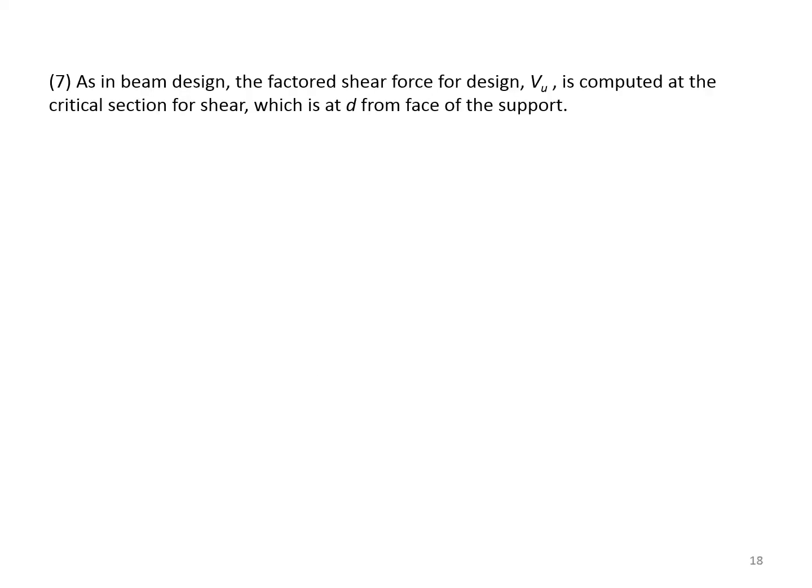Number 7. As in beam design, the factored shear force for design, Vu, is computed at the critical section for shear, which is at d from the face of the support.